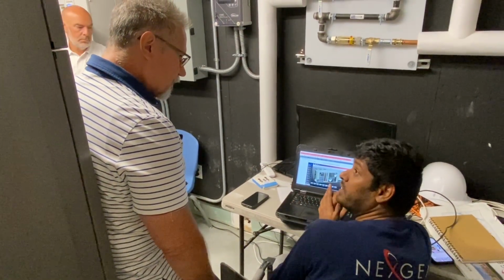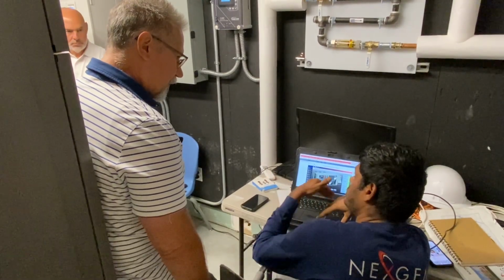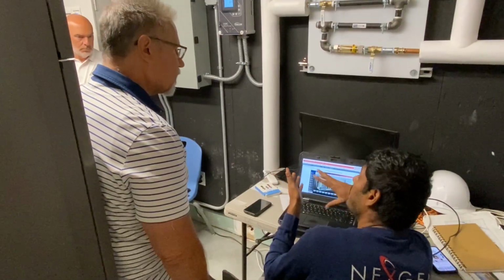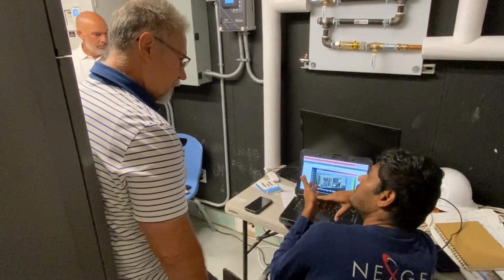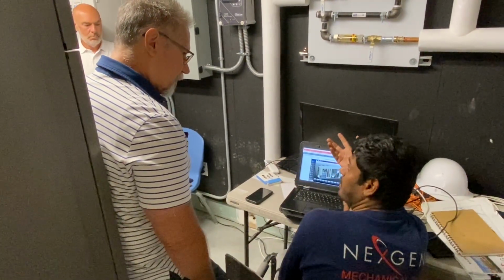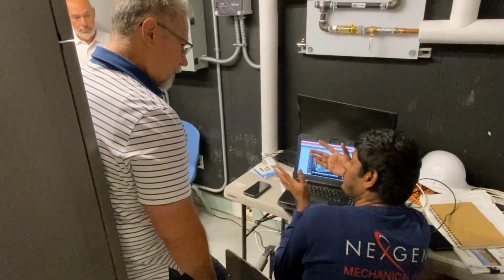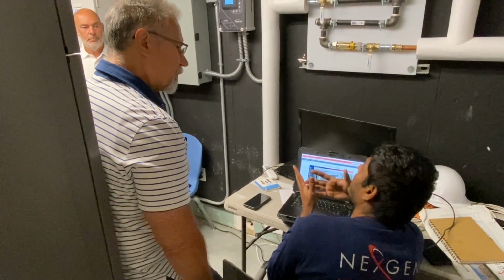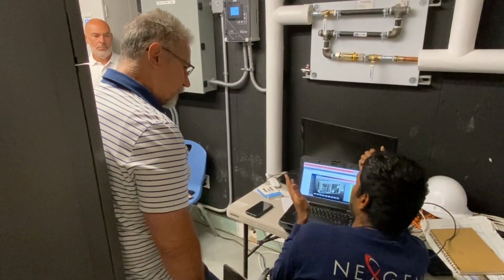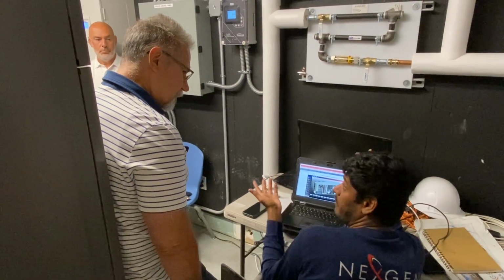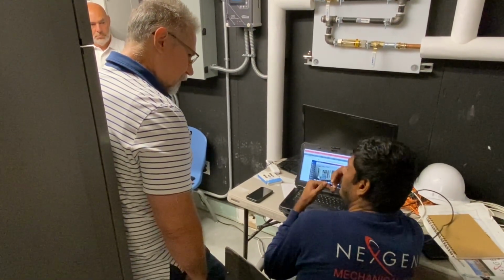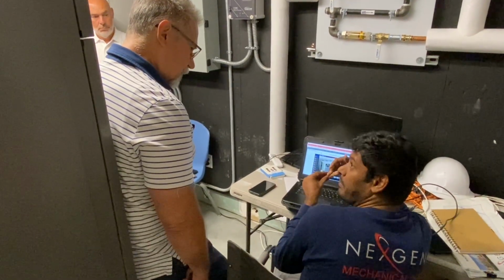We are averaging the space CO2 levels, and each VAV has humidity. It is integrated with humidity, CO2, and temp, right? So all the space CO2s are averaged, and that is adjustable. Right now it is 800 ppm. Let's say I have 20 VAVs in RTU1. What is my 10%? Like 2 VAVs, right? So if 2 or 3 VAVs go more than 800 ppm, then